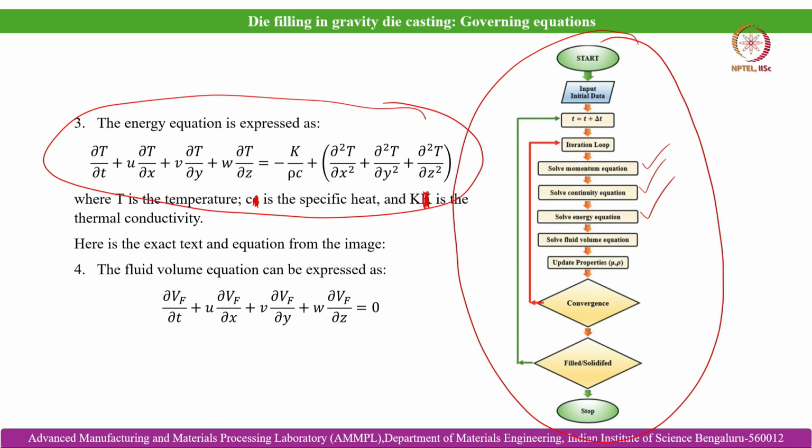And here is the fluid volume equation. In this case the fluid volume is also tracked based on the VOF technique. That is the resultant fluid volume equation. The VOF technique is basically used to track the free surface between the solidifying liquid melt and the air exposure at the top.